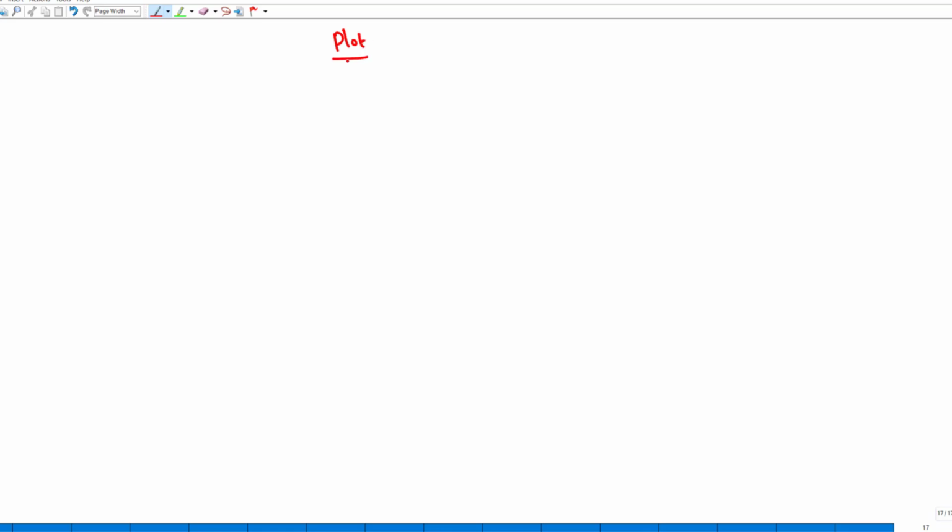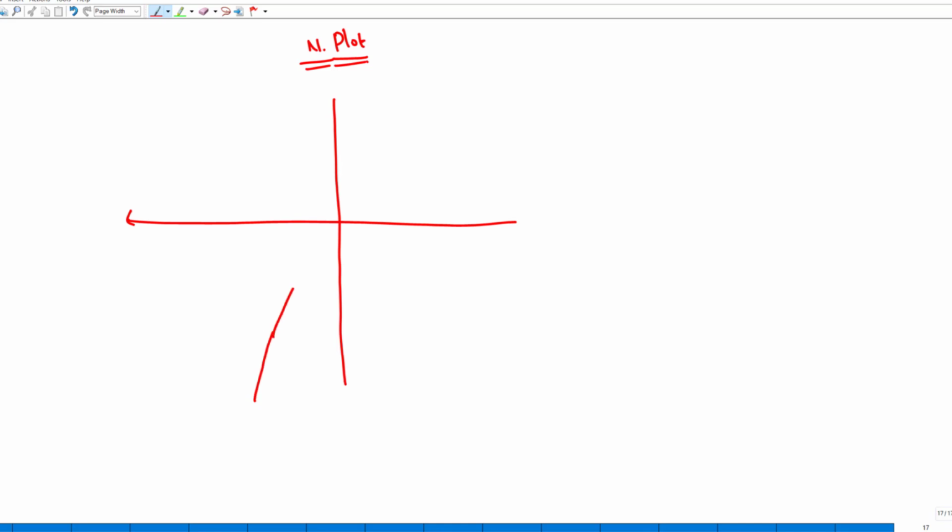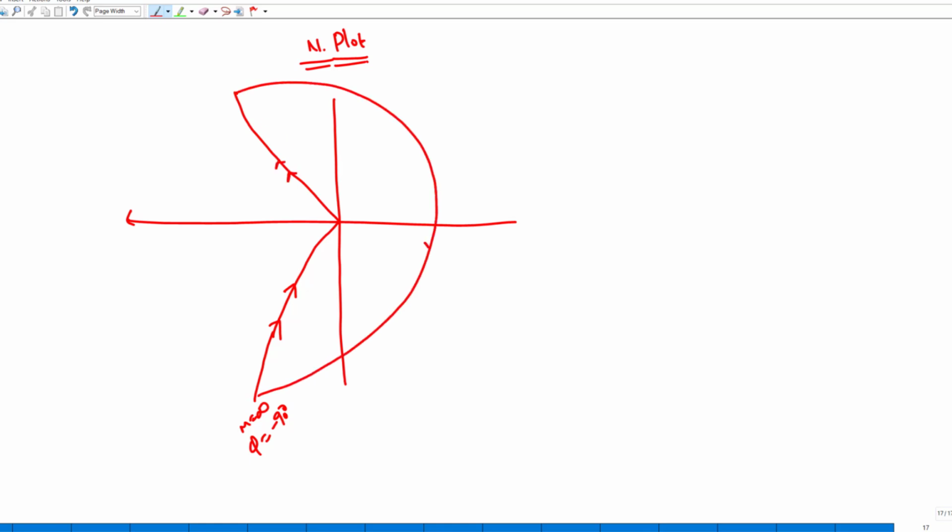So let us draw the plot here. This Nyquist plot you can draw here. When it is at infinity, it is touching infinity and going to minus 90. So the mirror image is infinity, minus 90, 0, minus 180, then the mirror image of that, and close it. Here the type of the system is also 1. So we will simply say that it is encircled only once.